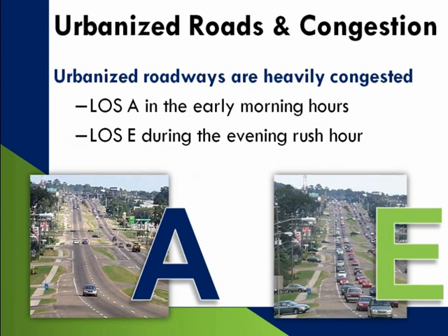Question often comes up, what's the level of service on a given roadway? And when you think about it, there is not a specific level of service. It really depends on the time of the day. In one case we could get A, in another case we can get E for the same roadway.